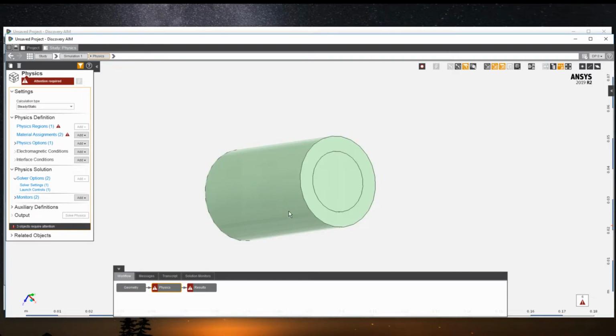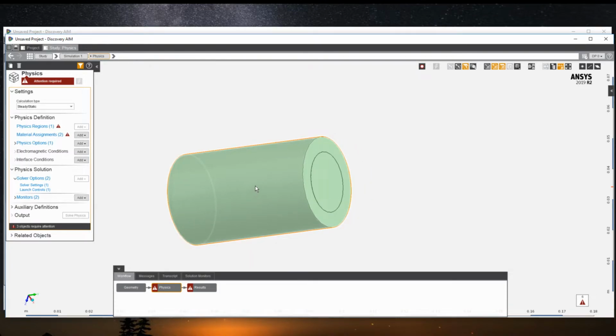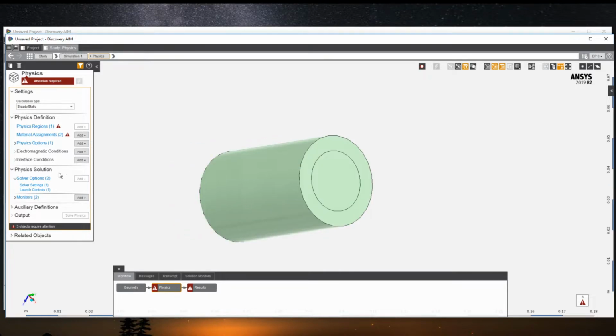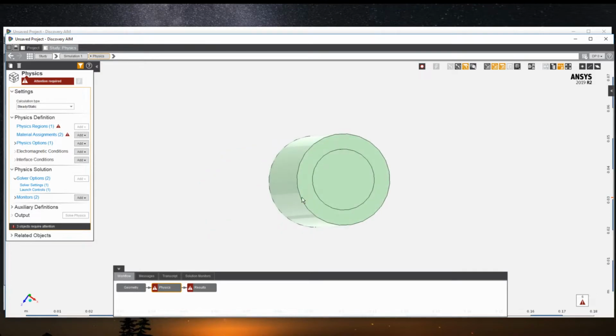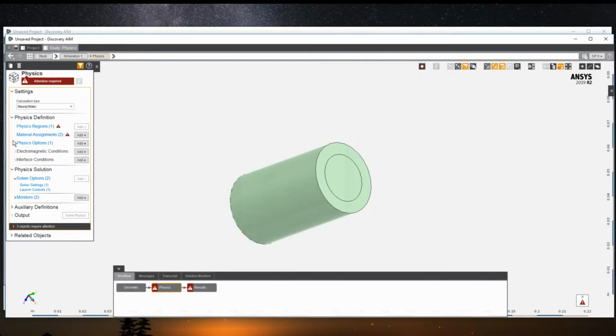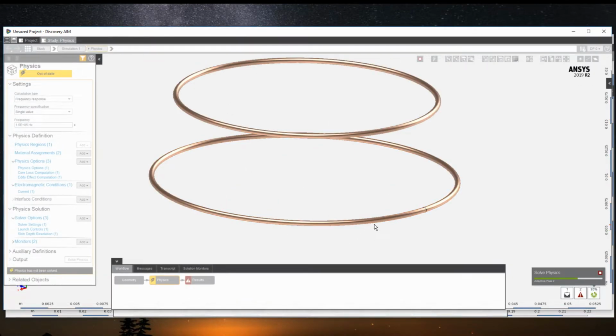You can enter the number. Let's say 100. You can enter 100, and it will treat it as a 100 coil in the simulation. But because we are doing a permanent magnet in this case, it doesn't give you the electromagnetic conditions for the applied current. So I cannot set it in this case. But yes, if you remember in this coil design, you can set the winding.